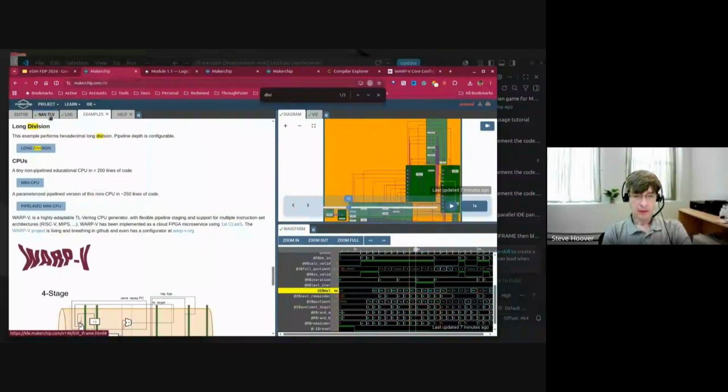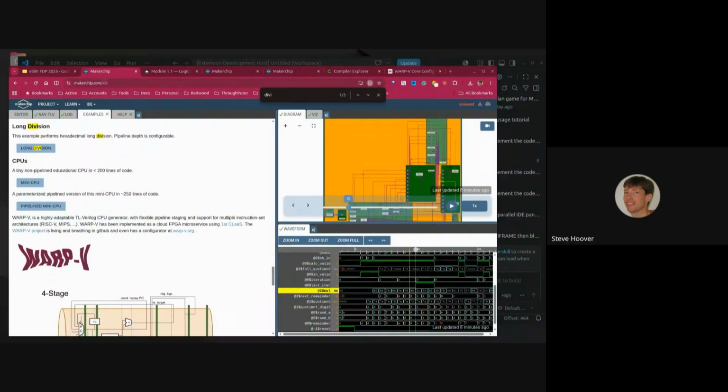In contrast to high-level synthesis, you have a community mainly driven by academia, which is focused on fixing the language limitations of Verilog and VHDL. So you have a whole bunch of languages that attempt to leverage the benefits of modern software languages, with a lot of capabilities that just don't exist in RTL languages. So any software language you can think of, there's a hardware description language that's built somehow on top of that language.